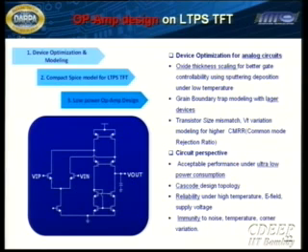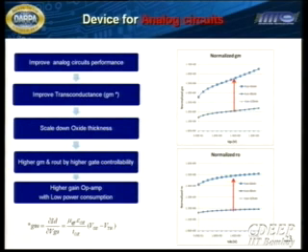So again, the similar kind of device optimization and modeling, and the modeling techniques are a little bit different, but here what we're really talking about is analog circuits. And I just wanted to mention that we looked at a very simple-minded op-amp. This is not the standard 741 op-amp, but a very simple-minded op-amp is what we looked at. And the idea is basically, from the analog circuit point of view, how can I improve transconductance. Ideally we need to scale our oxide thickness, but again, the quality of the oxide may not be the best. But how can I get higher gm and r_out, for higher gate controllability and so on, is what we've been looking at.